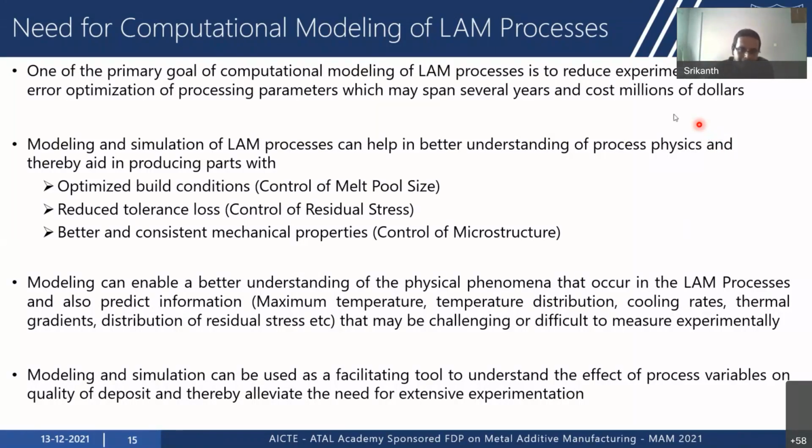Now, in many cases, there are process output characteristics that are difficult or challenging to measure experimentally, such as maximum temperature, the distribution of temperature, cooling rates, gradients, and so on. Modeling can provide a better understanding of these kinds of parameters and also enable us to predict them. We can use modeling and simulation as a facilitating tool to understand the effect of process variables on the quality of the deposit, and this will help alleviate the need for extensive experimentation.